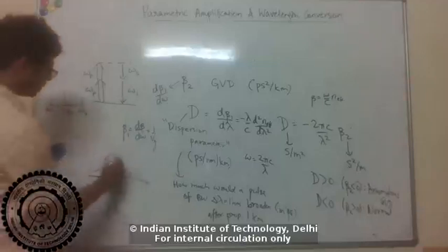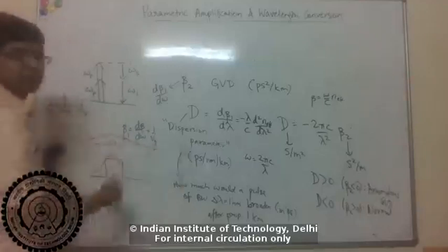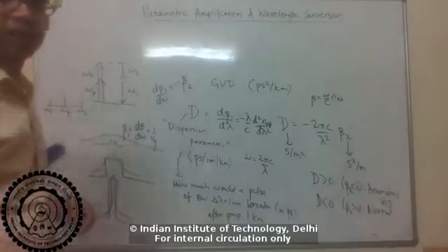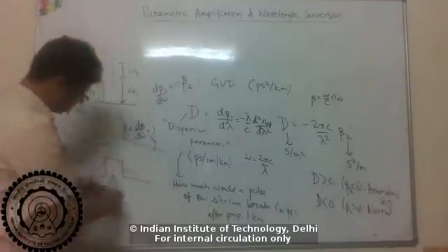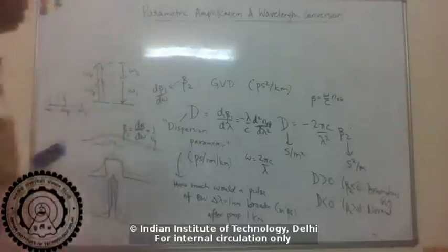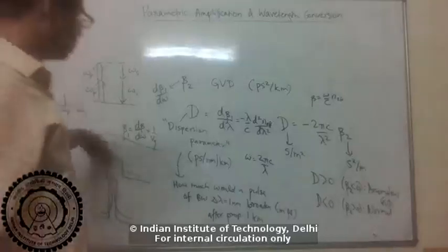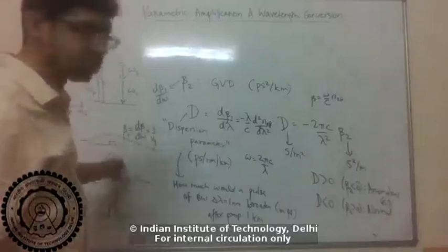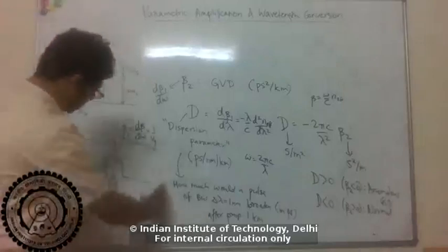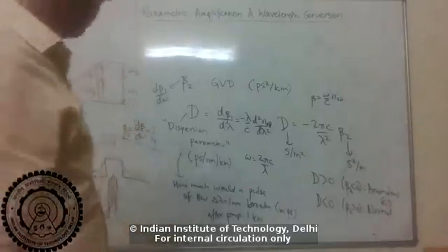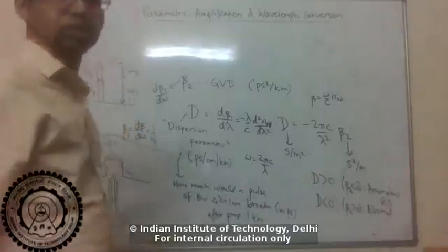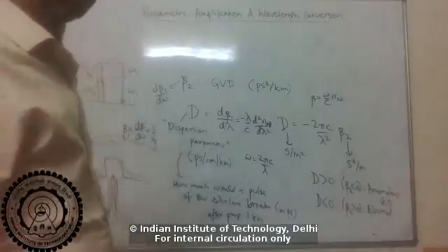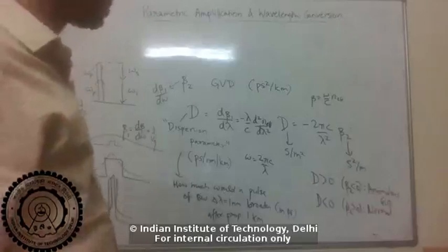Right? So this is the core and cladding. So if the difference is very small, then even if I start reducing the size of the core, the wave will still be spread out. So it doesn't really help. Whereas if the contrast is large, I can squeeze the wave to the core dimensions more. Yeah, that just comes from the solution of the Helmholtz equation, or equivalently, this is the same as, for example, the solution of the 1D Schrodinger equation in a potential well, right? If the well depth is more, then the wave is more confined. Similarly, if the refractive index contrast is more, then the electric field is confined more into the core. So, okay.